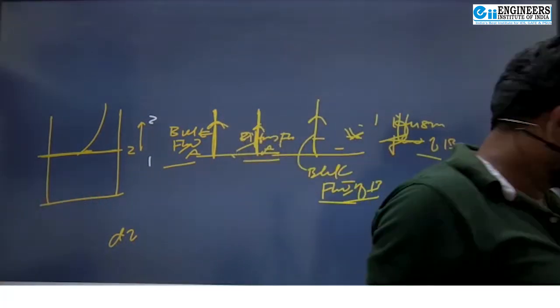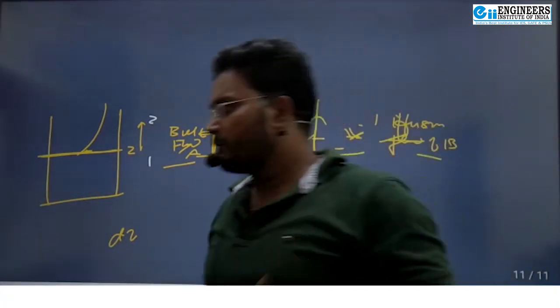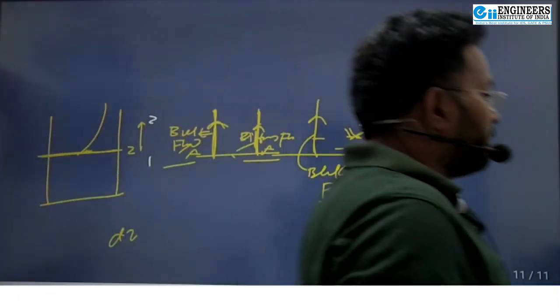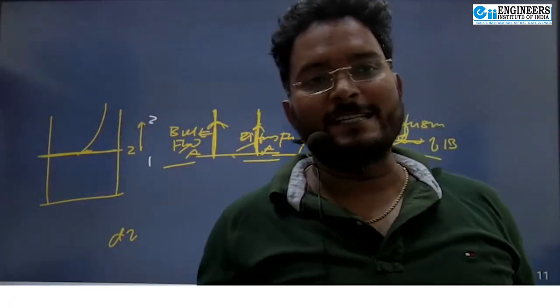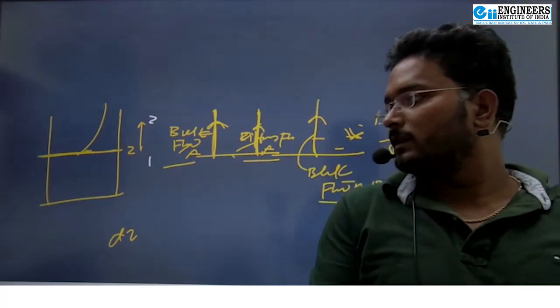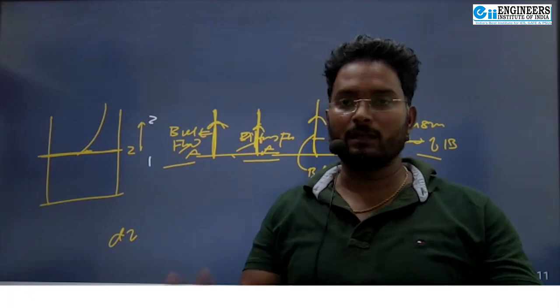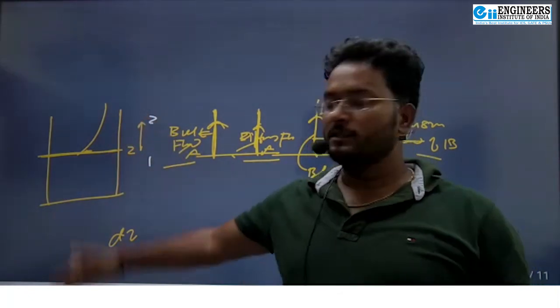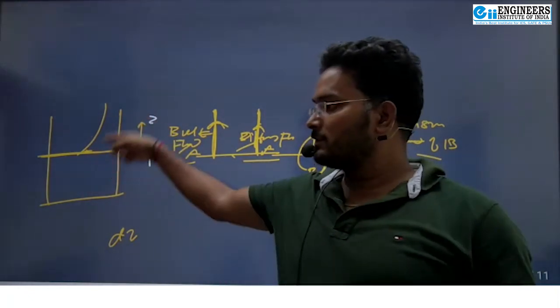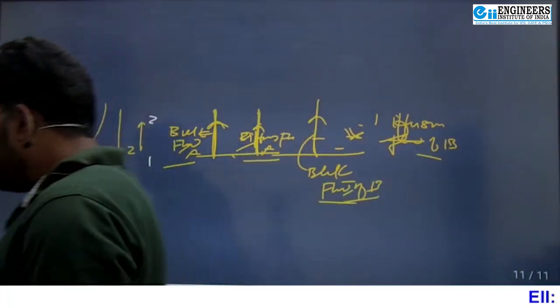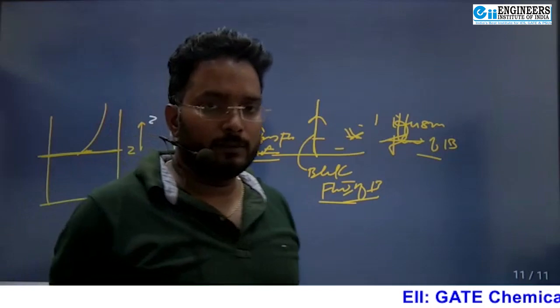Okay. So we have seen that in the case of equimolar diffusion the profile is linear, but in the case of A diffusing through non-diffusing B, NB must be 0 at each and every point in the diffusion path. Did you understand? At each and every point NB must be 0. So when the concentration changes, the bulk flow contribution will also change. The profile for A diffusing through non-diffusing B I will discuss by tomorrow.